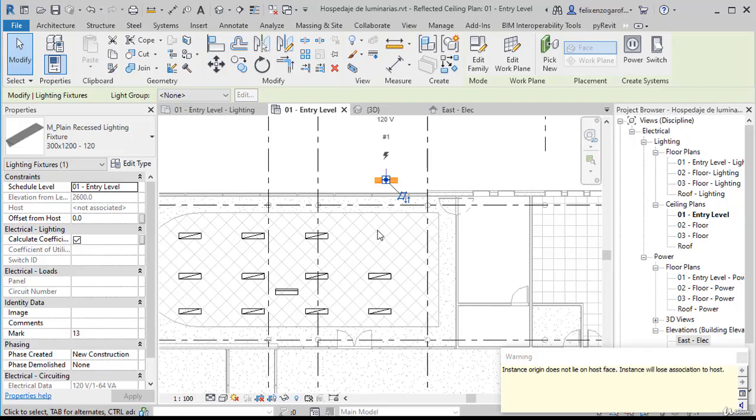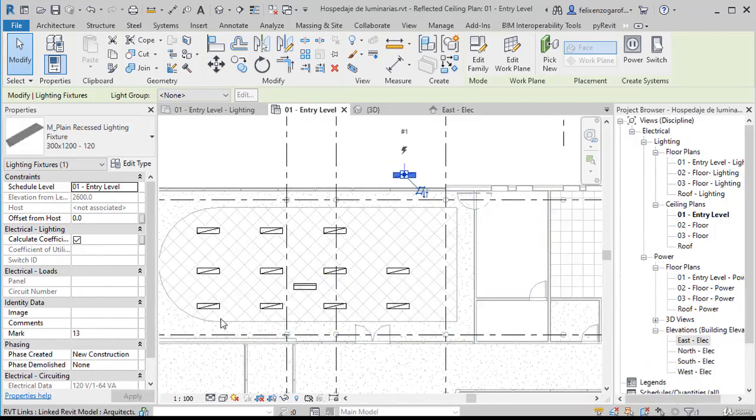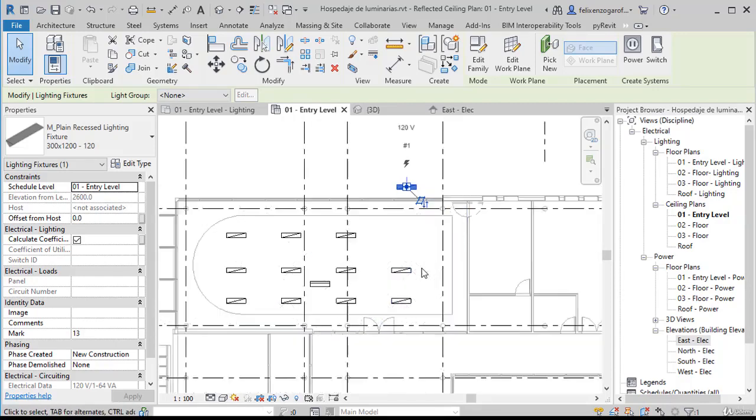If the ceiling height changes, the light will change height with it, but on a horizontal movement it will depend. In this case, you can see that the ceiling was created using a sketch. If these sketch lines move individually and end outside, we won't be able to change it. Now, if it is moved totally, there won't be any problem. Such situations have to be taken into account.